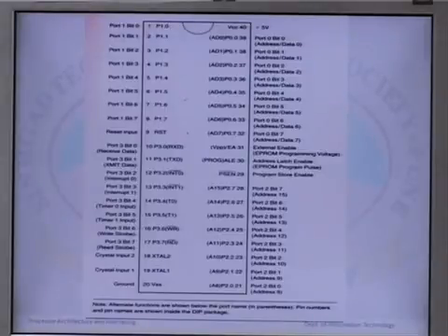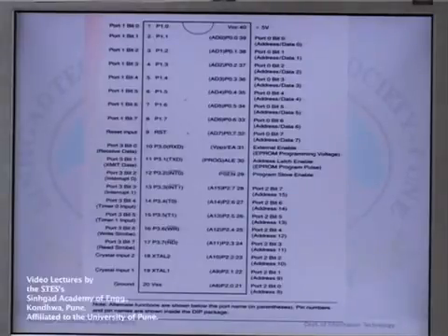As shown, pin number 32 to 39 are the port 0 pins. They are similar to port 2. If external memory is not used, these pins can be used as general inputs and or outputs. Otherwise, port 0 is configured as address output A0 to A7 when the ALE pin is driven high, or as data output D0 to D7 when the ALE pin is driven low.